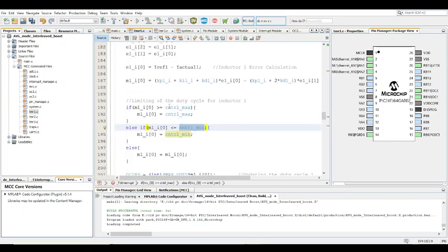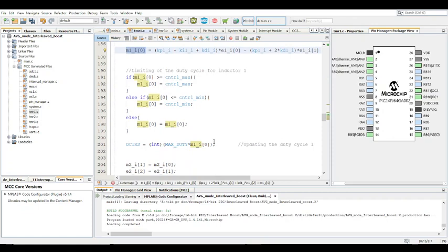So like I said, this particular routine is configured for a maximum of 1. If this puts out 1, that's 100% duty cycle. If it puts out 0.8, that's 80% duty cycle. So it's configured that way, and then at the end, it's scaled. The max duty in this case is 159, so it's going to be multiplied by that, because 159 represents 100% duty cycle on this particular microcontroller, which is not a super PWM resolution, but it's good enough. It will do the trick.